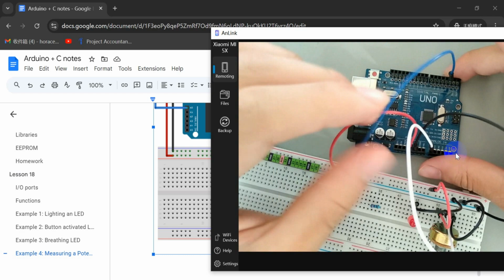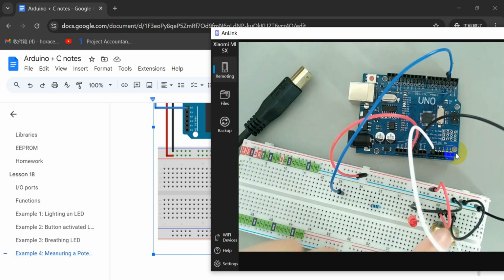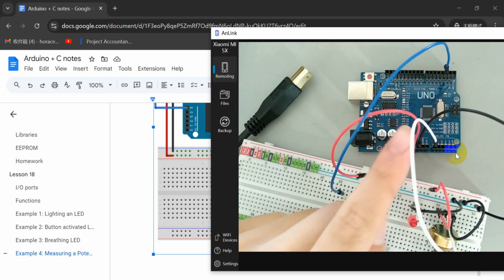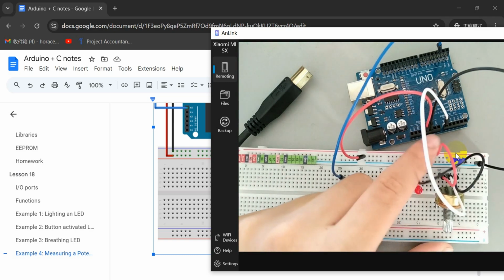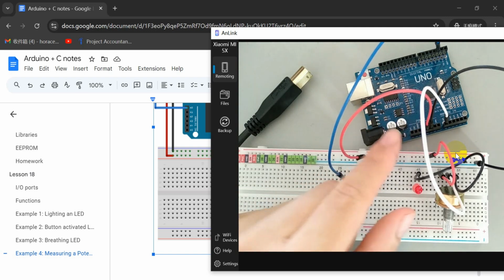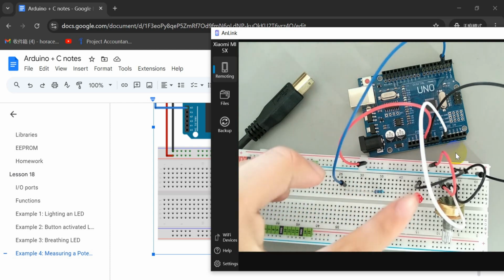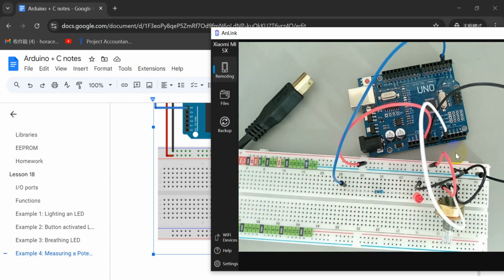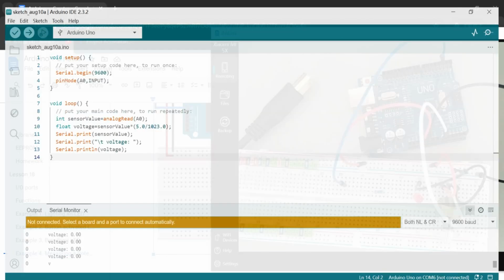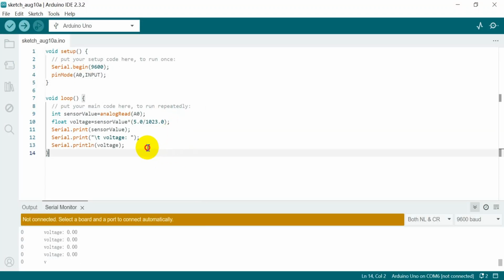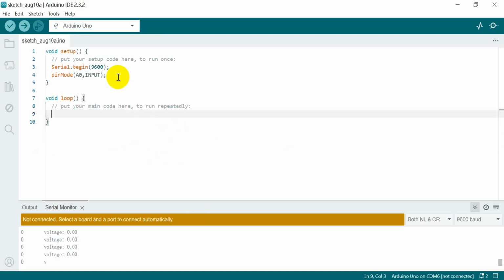Pin 3, like this. So now the value for the potentiometer goes in through the white line, and then some processes go on in the Uno board, and then through the blue line it comes back in here and turns on the LED depending on the value. So let's make this a reality with our code. We no longer need any of this. We will need a pin for 3, pin mode number 3, output.